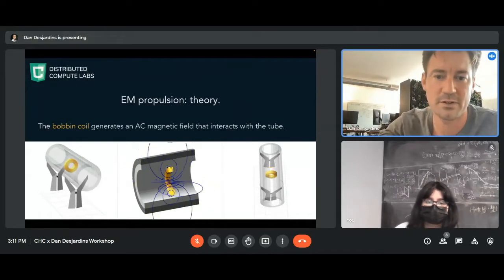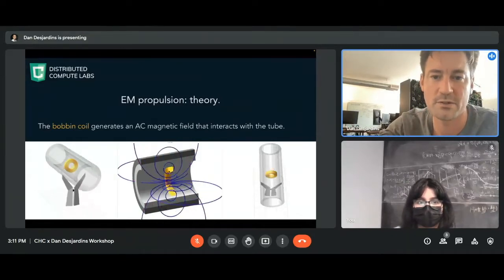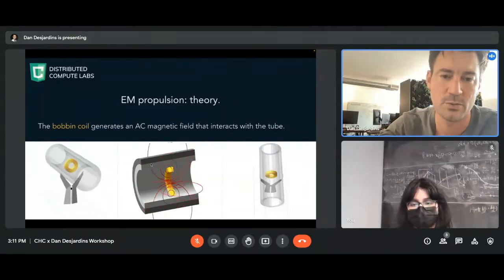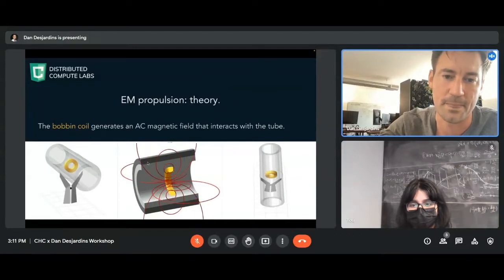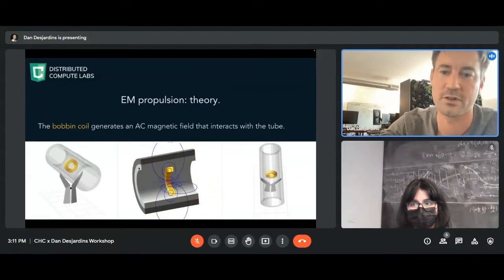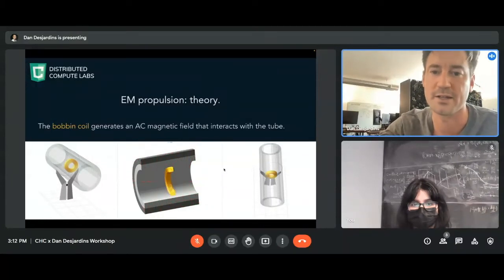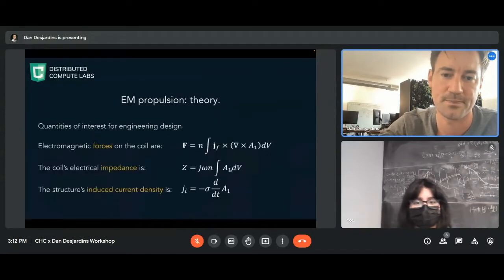So that was what I set off to do, is to solve the equations to figure out what the force felt by this coil would be for a coil that's pulsing at a certain frequency and moving at a certain velocity as it's traveling down a certain tube with certain dimensions and thicknesses of the inner and outer structures and different conductivities and different magnetic permeabilities and so on and so forth. Why? Because it'd be nice to be able to minimize drag and increase levitation and everything else.